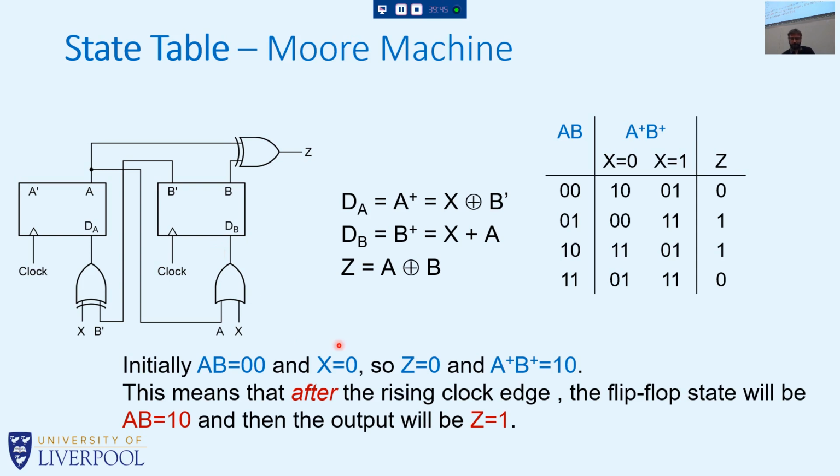So what we can do, and I'd invite you to look at the mini videos on signal tracing, but we can take, basically, if we say, okay, A is 0, therefore we have a 0 here. We know that X starts as 0, so we have a 0 here. If B is 0 to begin with, this is just initial information we've been given, then not B must be 1.